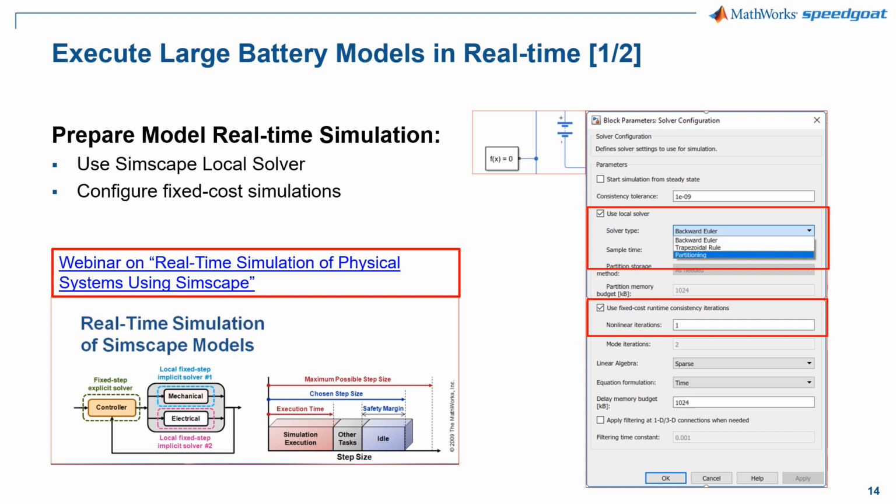We also note that for certain topology, partitioning solver improve performance by reducing computational cost of simulation. This helps in achieving faster simulation rate for both desktop simulation and real-time testing. The partitioning solver converts the entire system of equation for the attached Simscape network into several smaller set of switched linear equations that are connected through nonlinear functions. Computational cost is reduced because it is more efficient to calculate solutions for several smaller equation systems than it is to calculate the solution for one large system of equations.